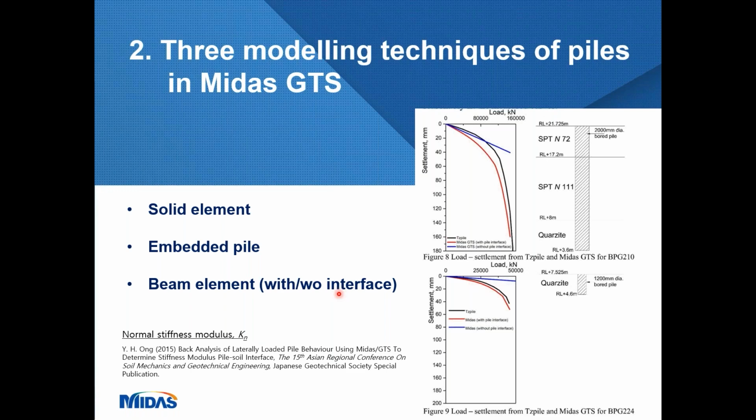Although the solid element is not very efficient in numerical modeling, it is very useful in modeling special situations where, say, you might want to model a low friction at a certain portion of your pile due to whatever reason, for example, a cavity problem or that the pile already collapsed.